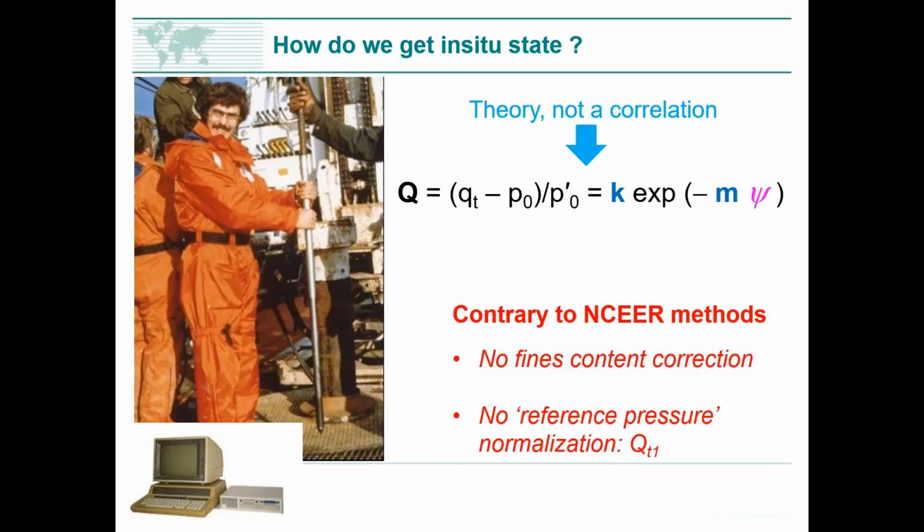This is the first digital CPT brought into Canada. This is in 1984. And we have a downhole analog to digital converter. We have downhole thermal compensation, and so on. It was a superb piece of kit. And not only that, we have digital transmission to the surface, and we then recorded it. And the little computer down the bottom you see, that was our data acquisition computer. And Gulf wrote the software for the data acquisition and processing.